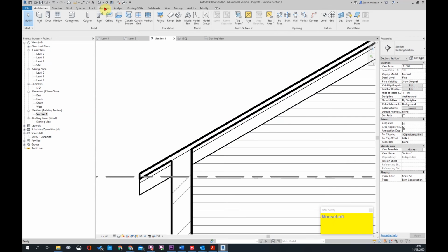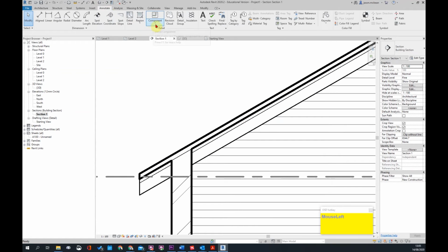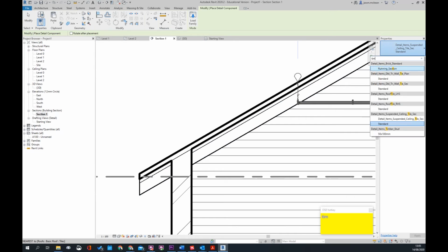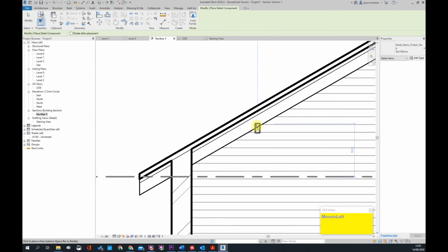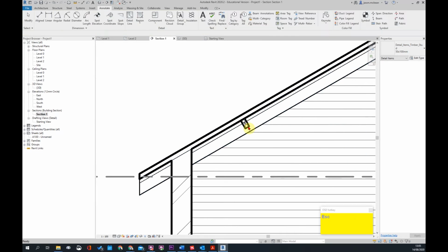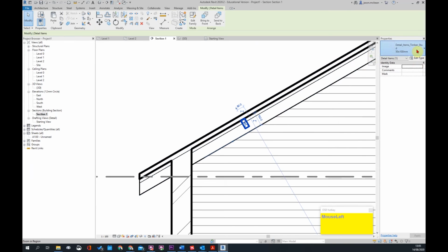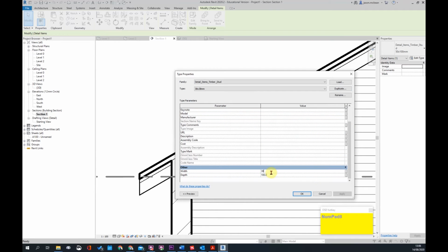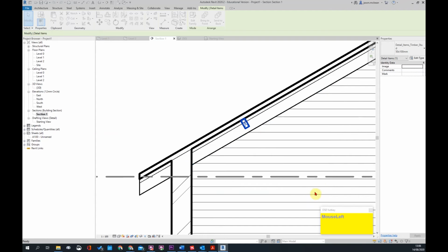And you can use a component here, which will be a timber section. Okay, and that will be a 38 by 38 timber batten, for example. Duplicate, and that will be a 38 by 38. Look, this is different for steel construction as well because you get different sizes, but in essence, I'm just going to give you guys a principle.